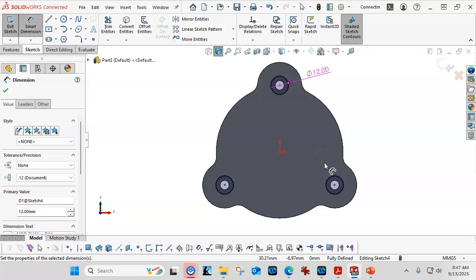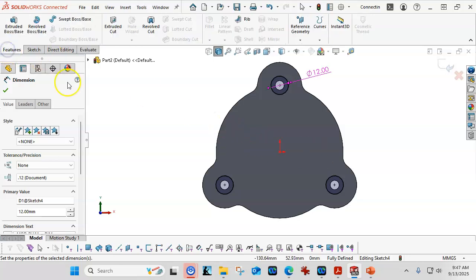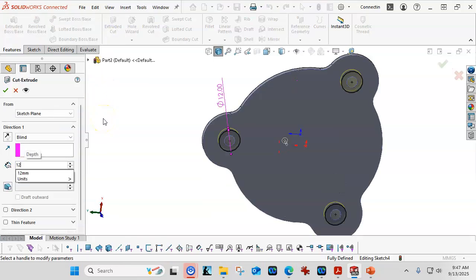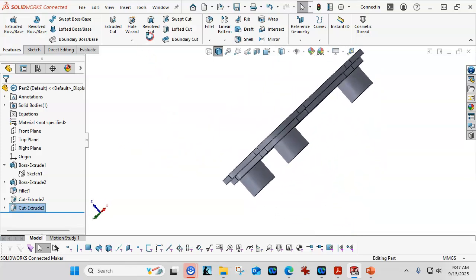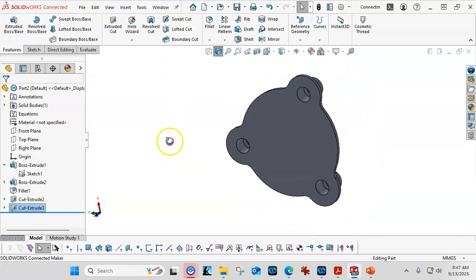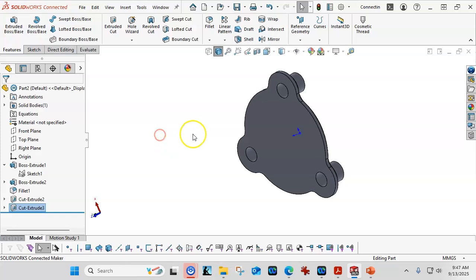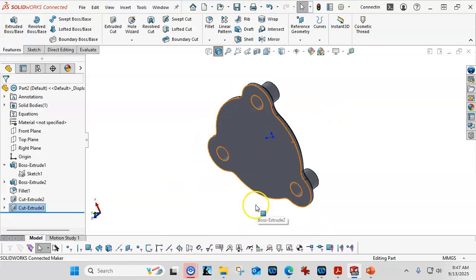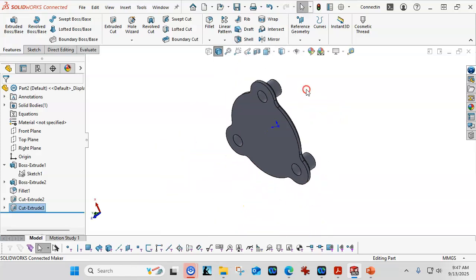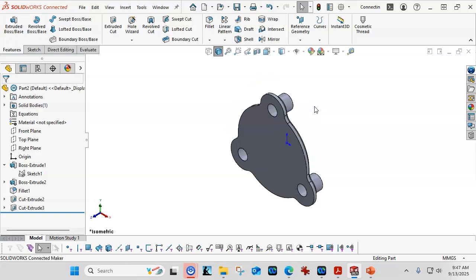We have the total overall height of 18. It is 6 millimeters off of the depth. So we're going to just cut in 12. And I will save the offset from surfaces a little bit later. So there is good reason in the design intent to say that this thickness would always be, if I have to make changes, and that would be where we use the end conditions for the offset from surface.